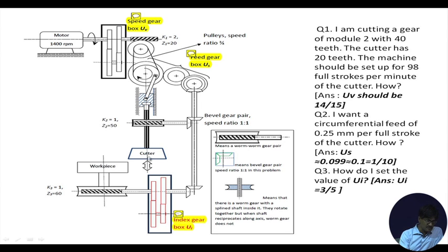We have made the cutter rotate, we are making the workpiece rotate here, and we will maintain the RPM ratio as if the workpiece is already having the required number of teeth. The cutter has a fixed number of teeth, this particular cutter, if you do not change it. So, now we are convinced that the single motor source, through these 3 gearboxes and some other mechanisms which we have discussed, is able to successfully reciprocate the cutter, rotate the cutter as well as rotate the workpiece.